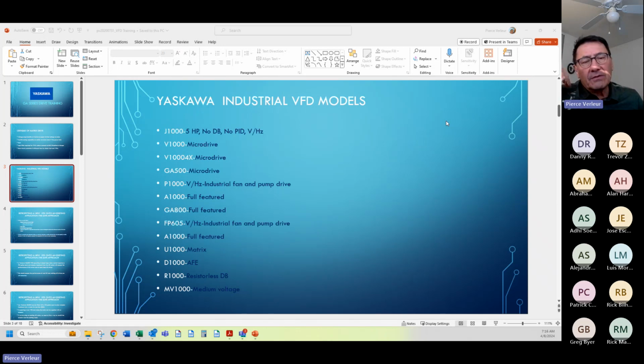Because NEMA 4X is rated for 100 pounds per square inch directed washdown pressure. And the X means that it can handle somewhat corrosive fluid. So, problematic application. Not a lot of volume, but in my opinion, necessary to keep you competitive against everybody else, because there are some other people out there with pretty good NEMA 4X designs. Above a micro drive, I absolutely recommend you do not consider that. Put the drive in a ventilated enclosure and put it outside of the washdown area.